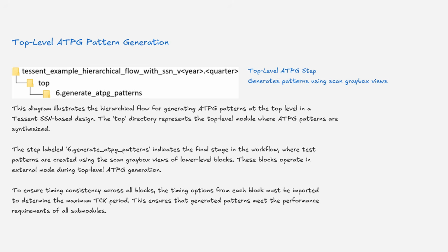To ensure timing consistency across all blocks, the timing options from each block must be imported to determine the maximum TCK period. This ensures that generated patterns meet the performance requirements of all submodules.